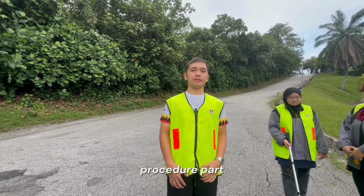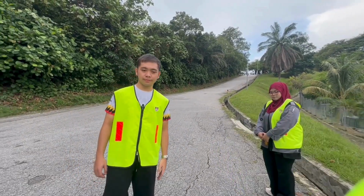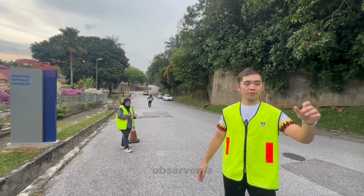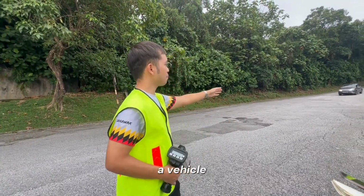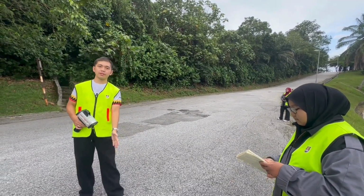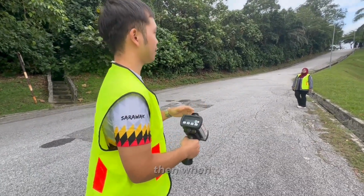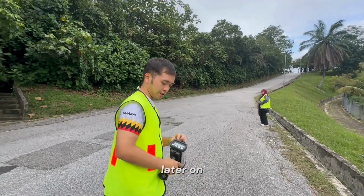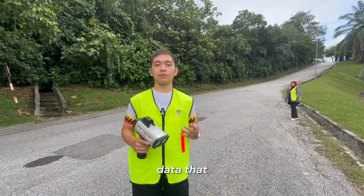So for the procedure part, firstly we need to measure from point A to point B, which is over here. We need to make sure the first observer is at point A and the second observer is at point B. When a vehicle passes through point A, a stopwatch needs to be started, and when the vehicle passes through point B, the stopwatch needs to be stopped and the time will be taken. For the radar gun, firstly we need to turn it on, and then when the vehicle comes, we just aim, push and shoot. Later on, the speed data will appear here. For example, 20 km per hour. So that is the data that we need to record.